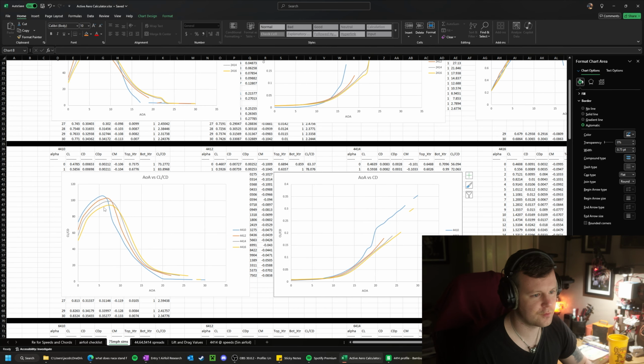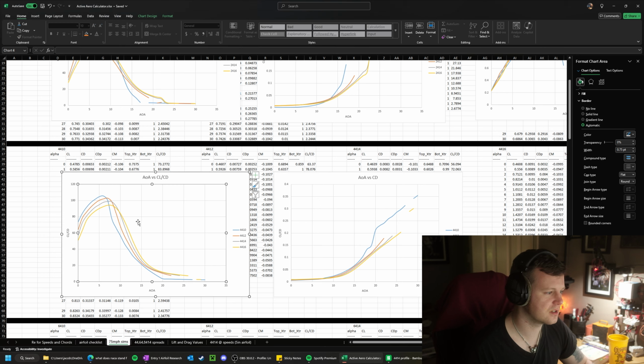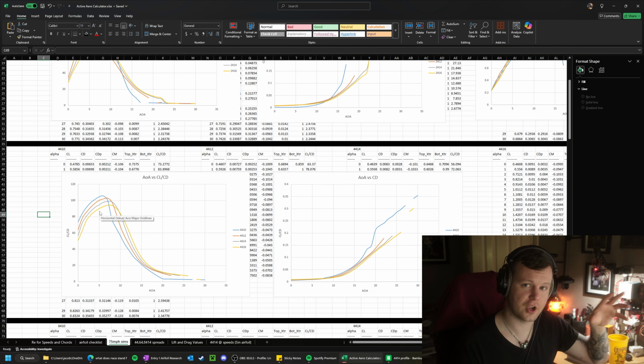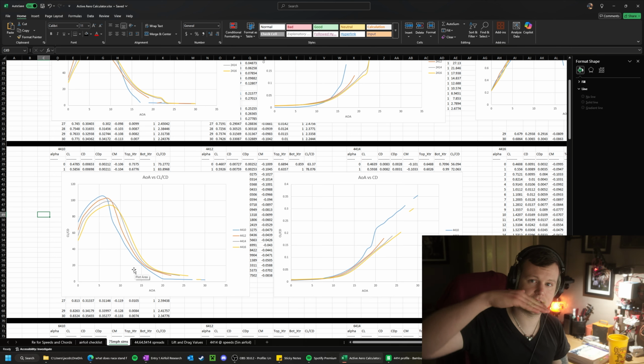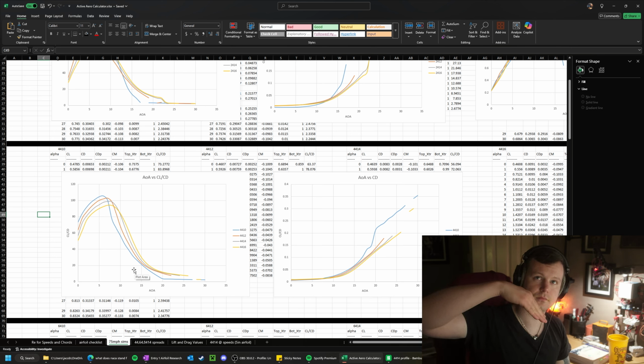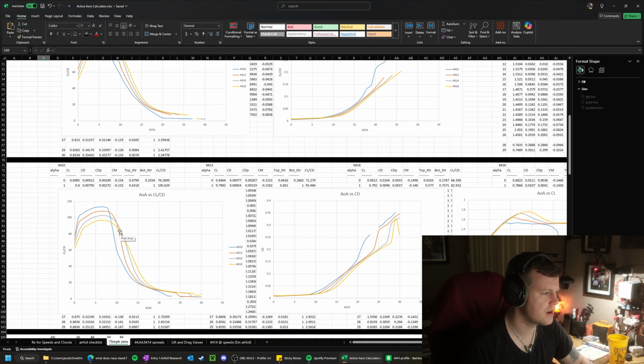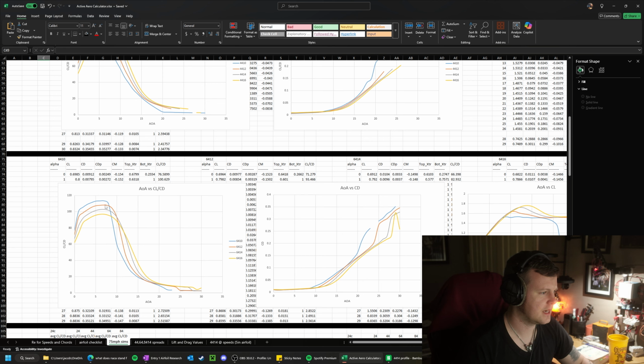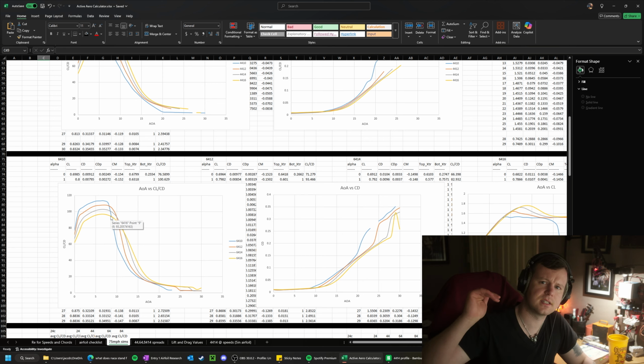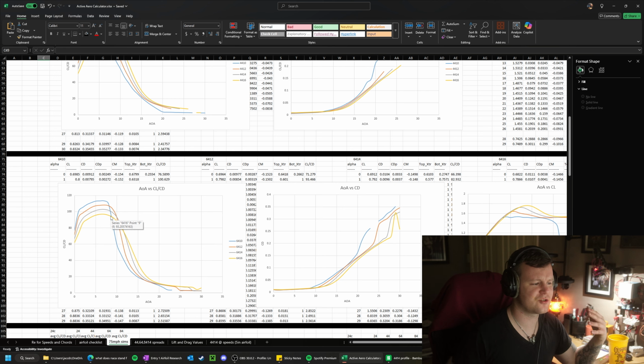But here we have the 4410, or the 44 series. I modeled 10, 12, 14, and 16 here. And you can kind of see the changes that those airfoils undergo as you change the angle of attack. That's how tilted the airfoil is. And here you can see the 6400 series, and this kind of starts flattening out right here. And I did CL over CD because it's just kind of a metric of an idea of how efficient the airfoil is, like how much lift are you getting for how much drag you're getting.